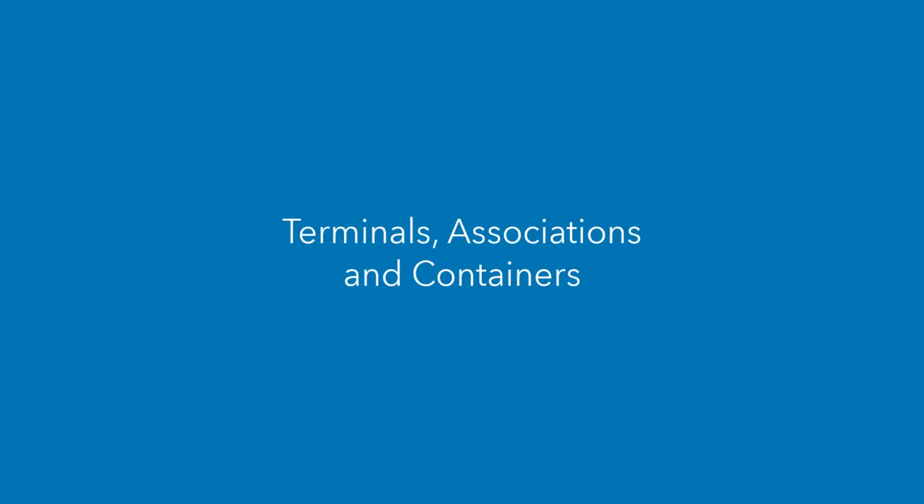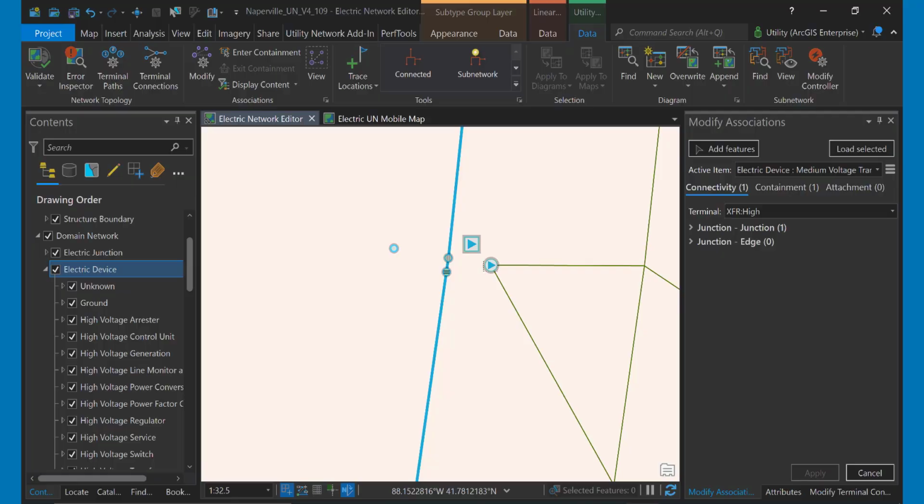Next, we'll talk about terminals, associations, and containment. Terminals within the utility network allow you to model devices to a higher degree of realism by using terminals on devices. Now, transformers, like this one here, have defined ports where electricity comes in and electricity goes out. The utility network allows you to model these ports by using terminals on devices. The terminals are not actual features you can see in the map. They're logical connection locations from devices that allows you to control how other features connect to the device.